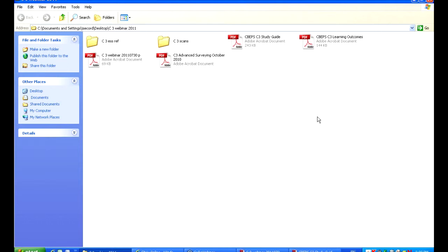If you do a foresight from, say, A to B, and then you occupy B and do a backsight onto A, the distances and the zenith angles won't be compatible because you will have different heights of instruments. So you have to take those values and reduce them to mark to mark.